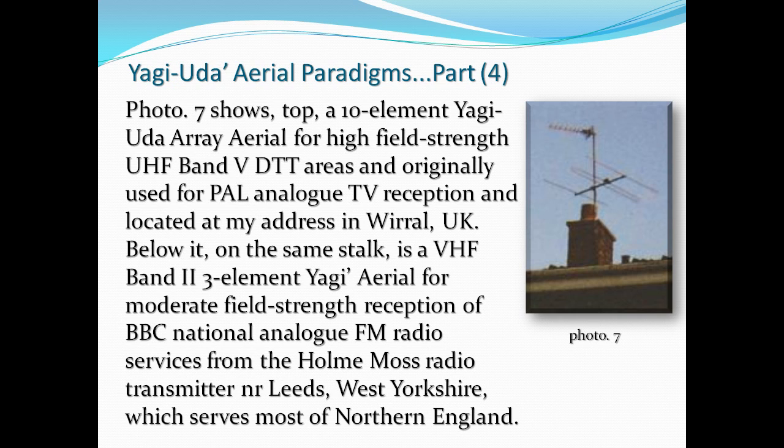If I added a further identical VHF band 2 Yagi aerial and combined it with my existing one so as to constitute a stacked arrangement of 2 such Yagis, I would significantly increase the signal voltage presented to the aerial circuit of my hi-fi's tuner component, but this value wouldn't be doubled. However, a cheaper alternative would be to use an active aerial amplifier located in circuit with my band 2 Yagi aerial. This would also provide much higher gain than that which could be achieved using the increased passive gain approach described here.